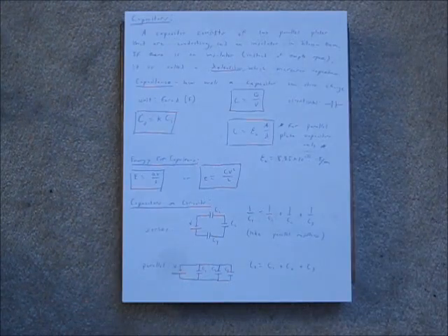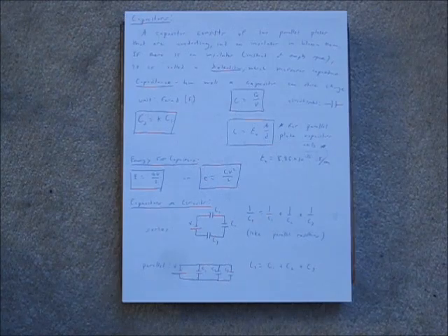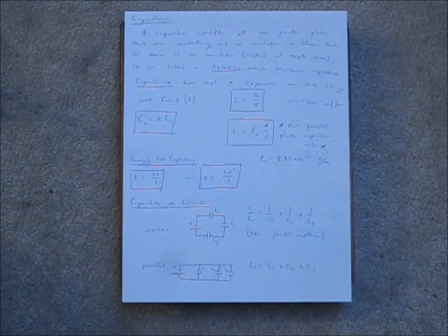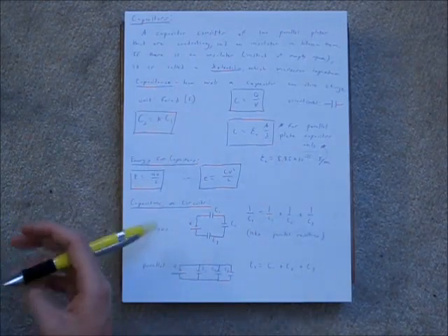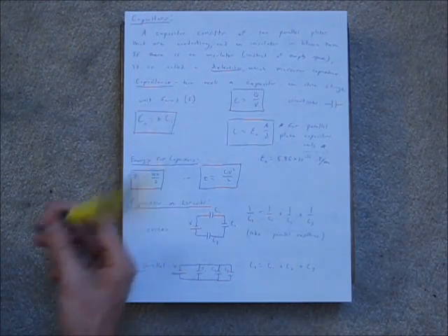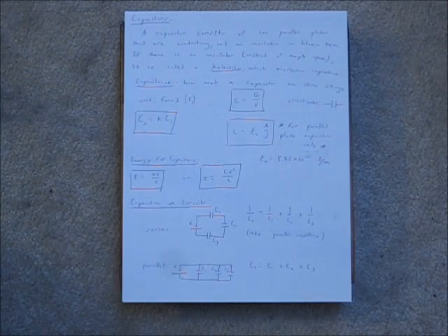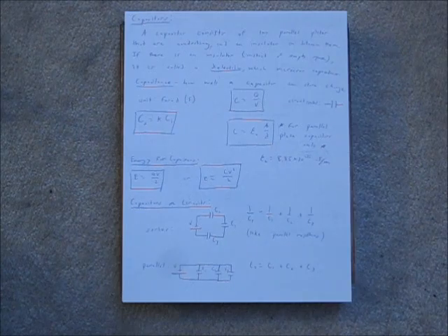A capacitor consists of two parallel conducting plates, and an insulator between them, or an empty space. The insulator between them would be called a dielectric, which always raises the capacitance. So if you have some initial capacitance and you insert a dielectric later, you would take that dielectric constant, which is different from the other k that you know, and you would simply multiply them, and you would get the new capacitance of the capacitor.